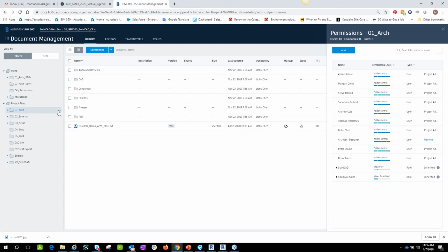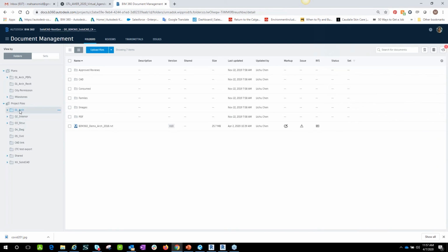The other thing I wanted to talk to you about is that if you're an architect and you want to always have access to the folder, and be provided the link whenever somebody is uploading a new sheet or Revit files that is going to be available for you to consume. And this is the new terminology, to be consuming. You can right-click and then subscribe to that folder. What this does is automatically generate an email subscription to your email address, the email address that you have in Autodesk, and provide some kind of automatic notification for your project.